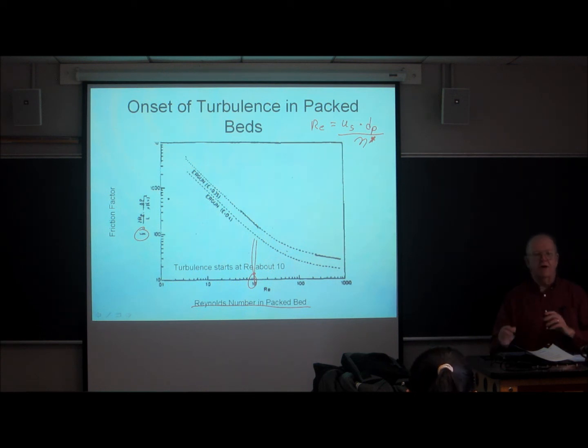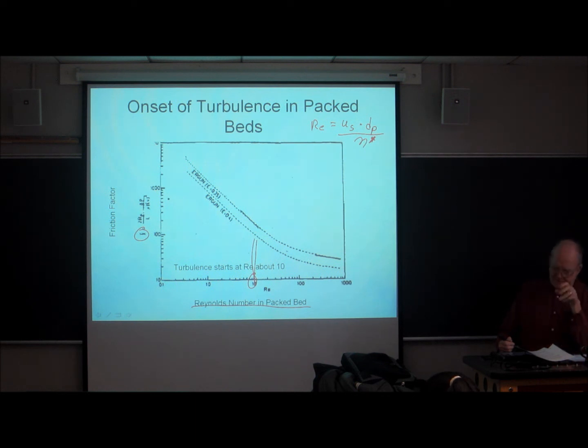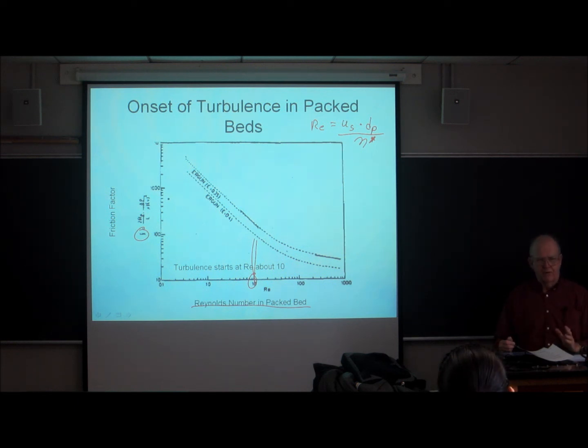If you put in reasonable numbers here, the Reynolds numbers hardly ever get much above 0.1 or 0.2, which means that we're really under laminar flow. And not only that, but the Reynolds numbers that we work at in LC are referred to as creeping flow. Creeping. That means extremely low flow. And I'll show you some pictures next time about what creeping flow really means.